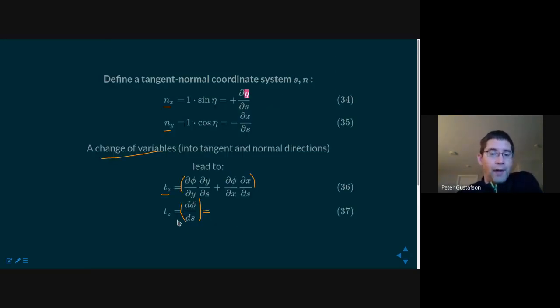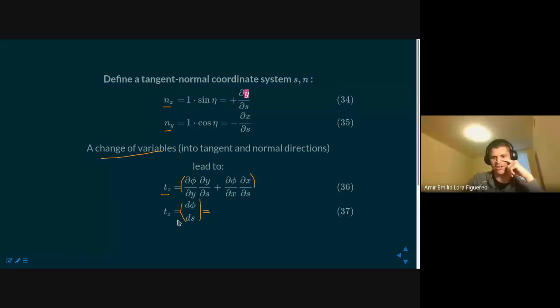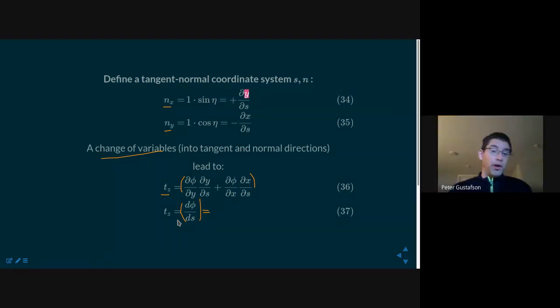Okay, so all of that being said, we need to circle back to this idea of a traction vector on a lateral surface of this thing. Okay, keep in mind I'm torquing the end of the shaft like so. What is the traction vector in the middle here on the exterior surface? Would it be 0? Yeah, it sure would. Why? There's nothing applying a stress to any of those exterior surfaces.